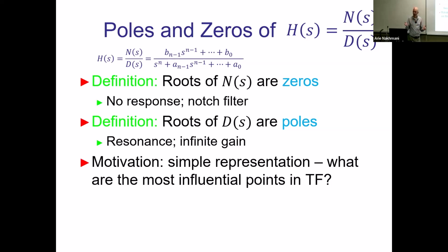Because you have factorization of the polynomials, you can factorize each one of these polynomials. Knowing the roots, you know the entire polynomial up to the coefficient, obviously, right? So the only thing you need to know, location of the roots, that coefficient of the gain, and you know the entire transfer function. So this is why it is so important.